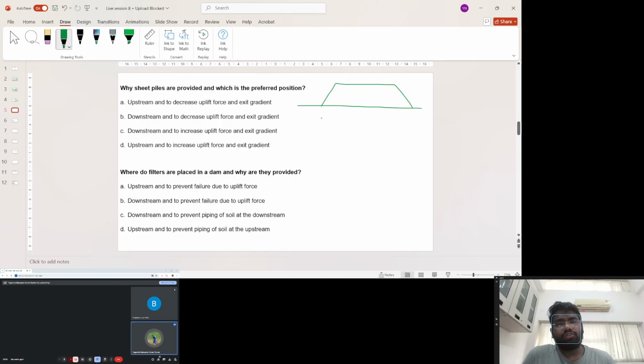So as the flow progresses, the water exerts a pressure, which is the seepage pressure or uplift pressure. The pressure exerted by water will be equal in all the directions. So the structure is going to get affected due to the magnitude of force that is acting upwards. Hence it is known as uplift force.